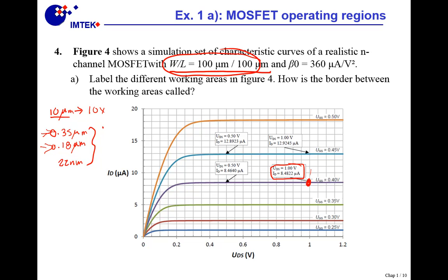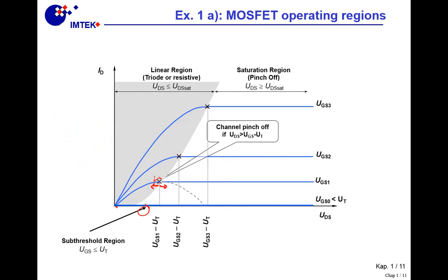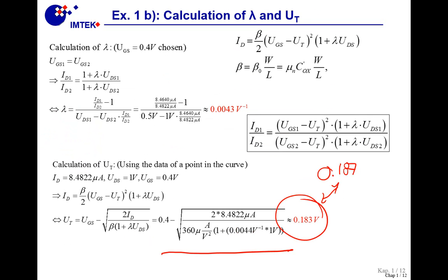Whereas when you have very small transistors, then the channel length modulation takes a big role. Okay? In this case, in our calculations, we have a difference of what? 3 millivolts, 4 millivolts, sorry. So okay, some people can say this is a lot. Some people can say that this is not so much. Nevertheless, you have to see that it's actually not the same.